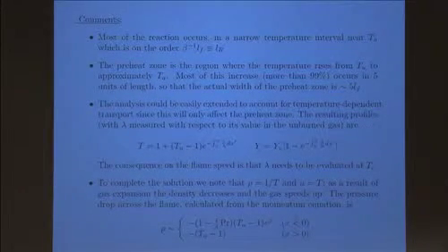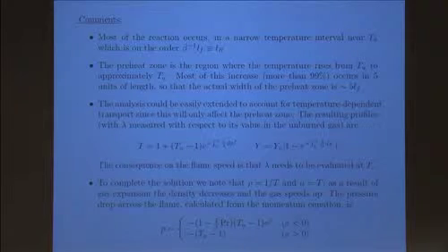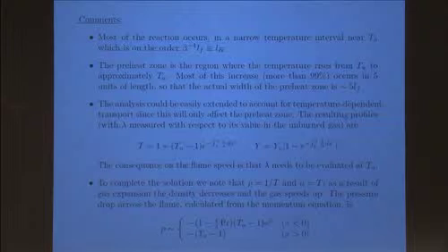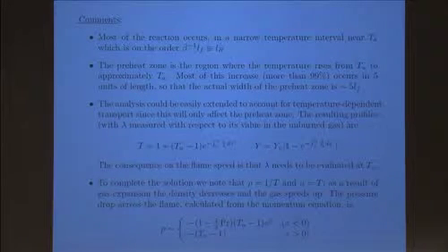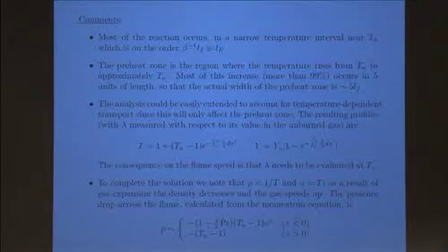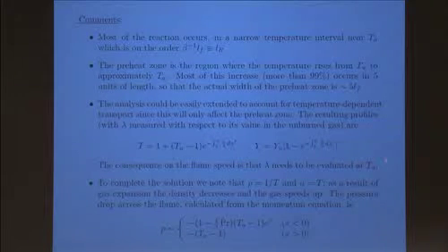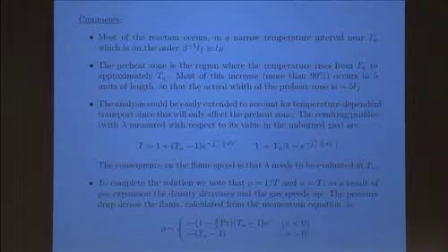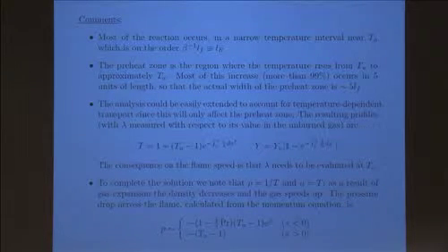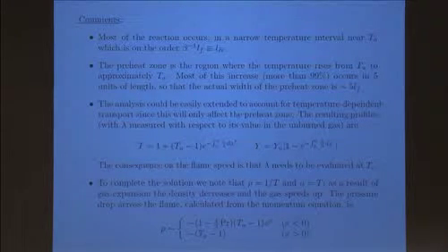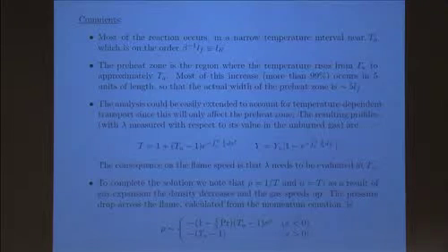And clearly, lambda is here dimensionless. In other words, it's scaled with respect to the conductivity of, say, the unburned gas. And so when lambda is 1, of course, you recover the previous solution. Lambda doesn't vary with temperature. Otherwise, there is a slight variation. And the change in the flame speed expression is going to be to evaluate lambda in that expression with the value on the burned side, because that's the most important region where the flame speed relation came from. And so that's easy to do.